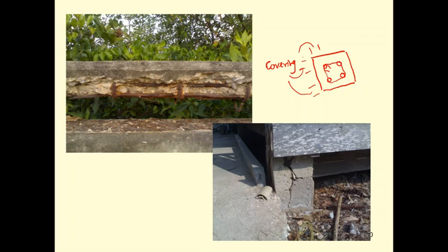In a normal structure, such as a column in the building, this covering can be just 24 millimeter to a maximum maybe 50 millimeter for outside. But if your structure is near the sea or in the sea, this covering should be at least 75 millimeter in order to have protection so the water won't penetrate into the steel and get rust. If you have a very thin covering, when the water reaches the steel it can rust.